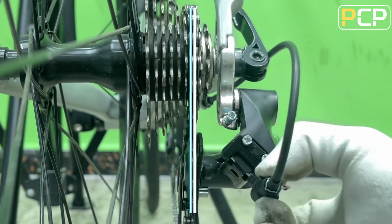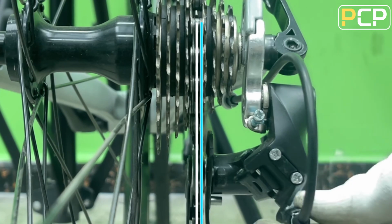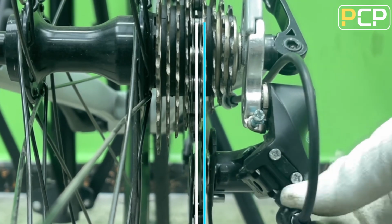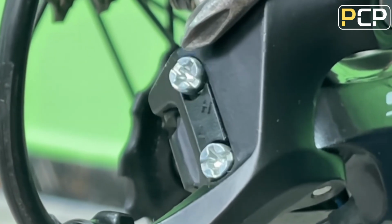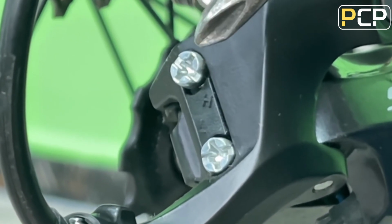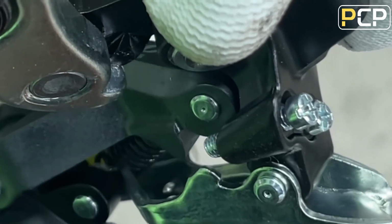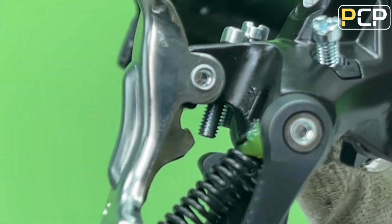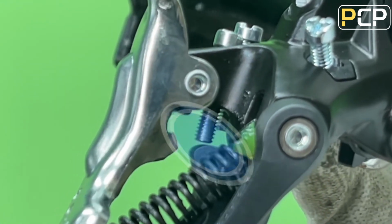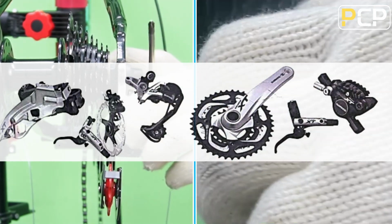The internal derailleur is sealed within the shell of the hub gear, in contrast with derailleur gears where the gears and mechanism are exposed to the elements. Hub gear systems generally have a long and largely maintenance-free life, though some are not suitable for high-stress use in competitions or hilly, off-road conditions. Many commuter or urban cycles, such as European ones, are now commonly fitted with 7-speed gear hubs, and 8-speed systems are becoming increasingly available. 3. The selection of the transmission system.